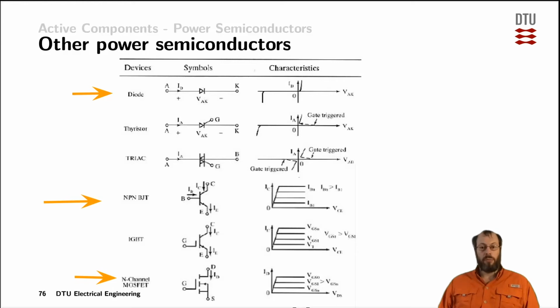In fact, bipolar junction transistors are rather rarely used in modern power electronics, and their usage is reserved to circuits operating in the microwave range, as they are still the fastest devices that we can get to operate electronics. In between a bipolar junction transistor and a MOSFET, we have the so-called IGBTs.